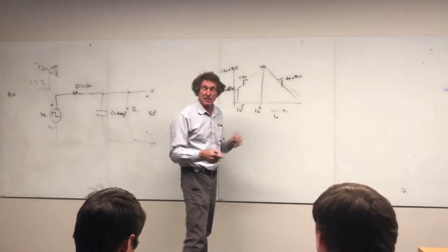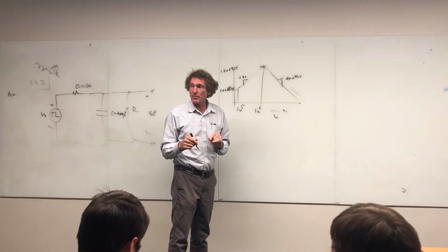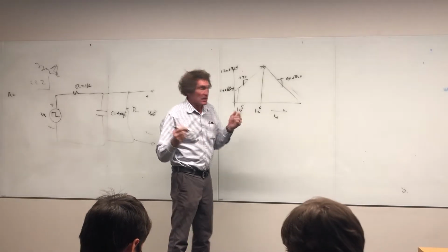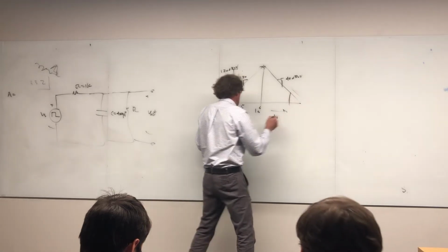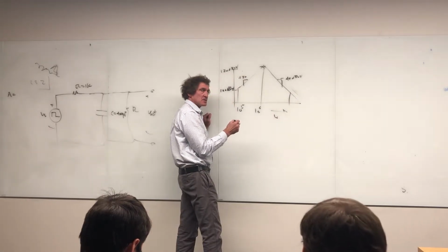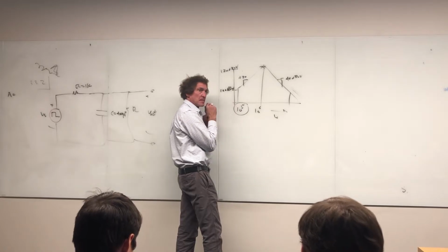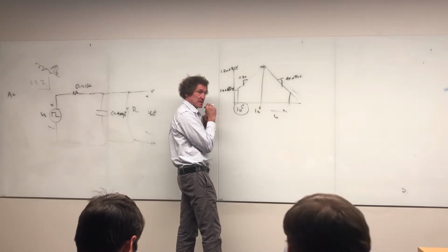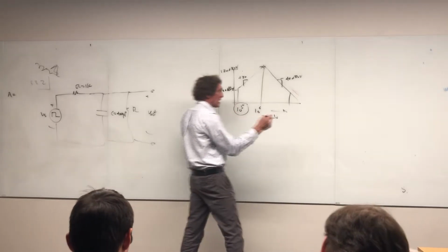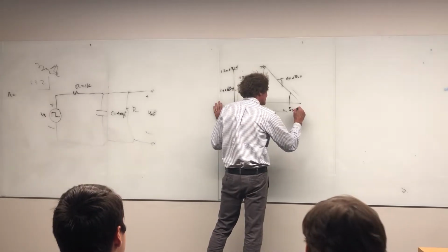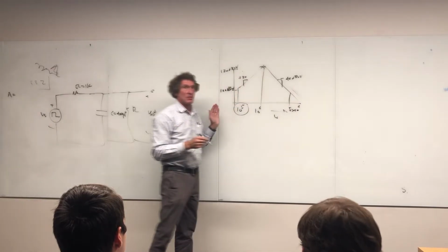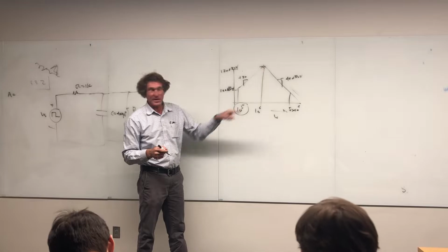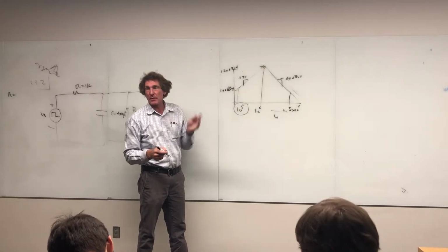All right, now that's the input. Where does he want it? The output voltage, right? At what frequency? 50th harmonic. All right, you're way out here. This is omega naught, is it not? Yes. If that's omega naught, it's 50 times that, or 5 times 10 to the 6, correct, class? Yeah. So out here is 5 times 10 to the 6, and he wants to know what the output voltage will be, right? So first of all, what's that signal level that would be going in?